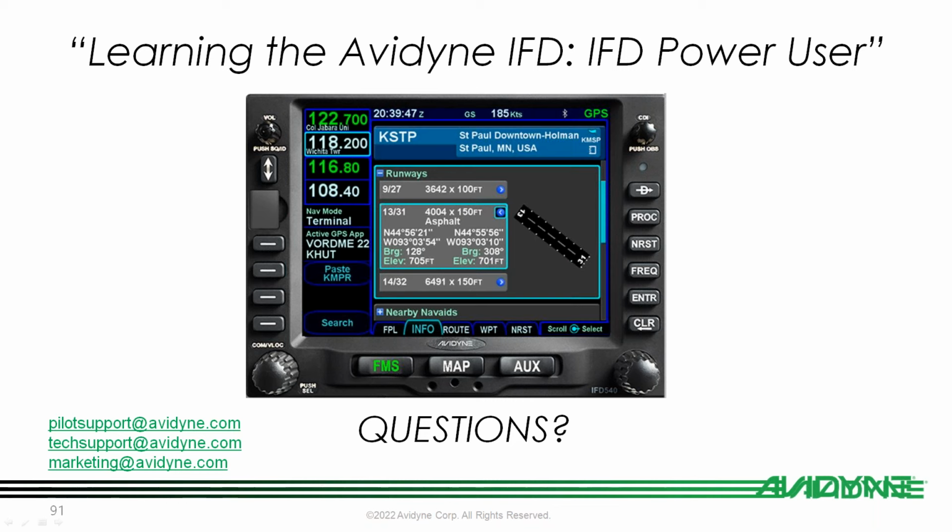Joe asked about data blocks on the left side of the IFD 440. Are you able to customize that? Is there not enough room? Usually there's not enough room. With the 440, because the screen is so small, it tends to get used up by the line select keys that are there, or the COM or nav blocks. With the 4 series, you also notice that you only have one of each type, either the COM or the nav, available as data blocks on the left side. Of course, we toggle those just by pushing that left button. There's just not a whole lot of real estate on the left side of the 4 series to get some custom data blocks.